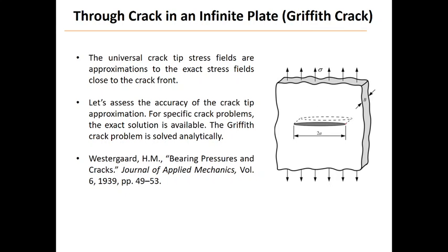So this is the Griffith crack problem, or sometimes we call it a through crack in an infinite plate. Basically, the plate is infinitely large, and you have a crack in there with tensile stresses applied on both sides. So we have the complete stress field all over the whole plate. Or sometimes these days we can compare solutions to finite element, but back in the day there was not. So we compare to analytical solutions.